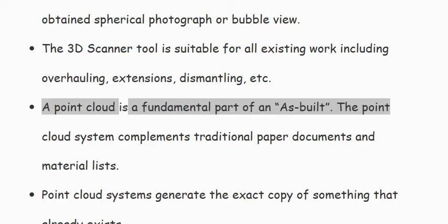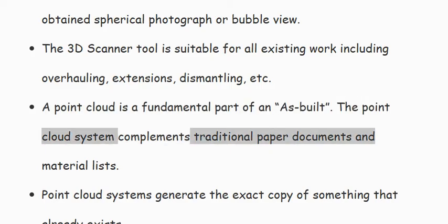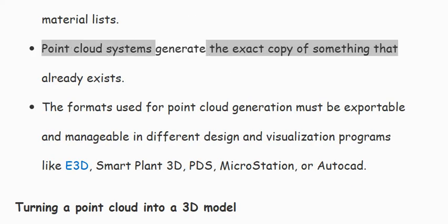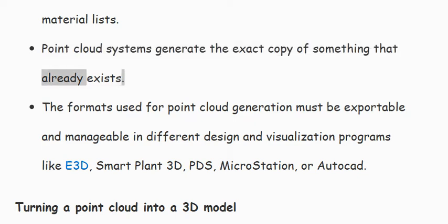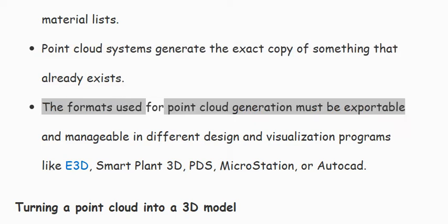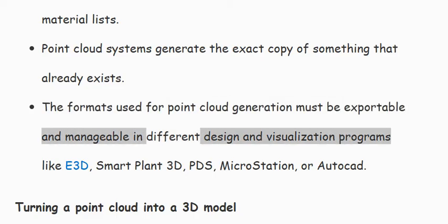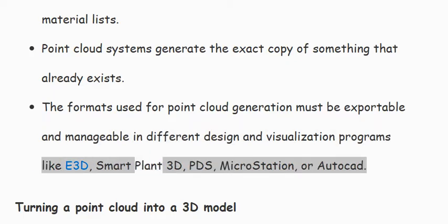A point cloud is a fundamental part of an as-built. The point cloud system complements traditional paper documents and material lists. Point cloud systems generate the exact copy of something that already exists. The formats used for point cloud generation must be exportable and manageable in different design and visualization programs like E3D, Smart Plant 3D PDS, MicroStation, or AutoCAD.